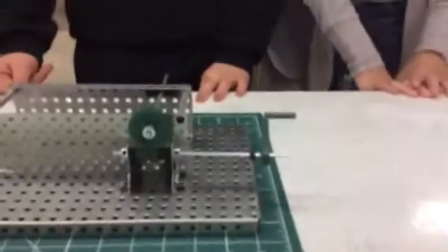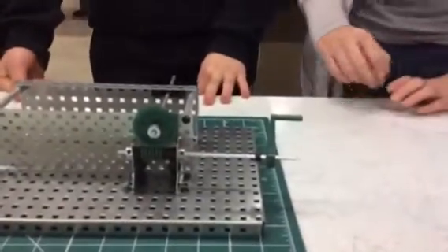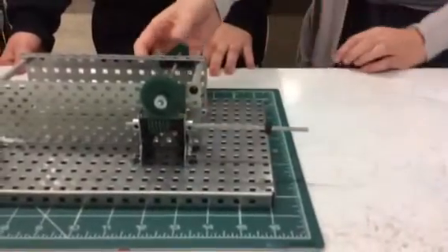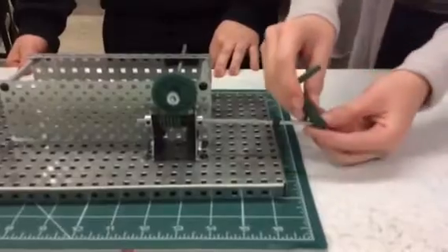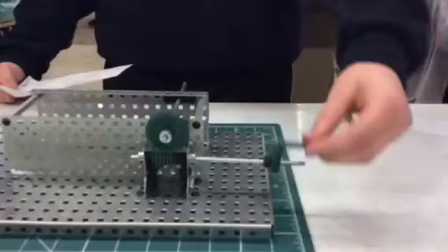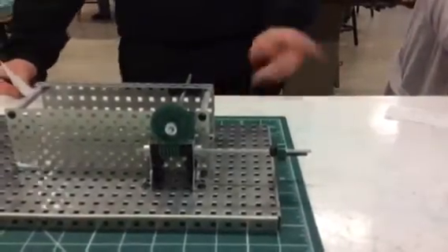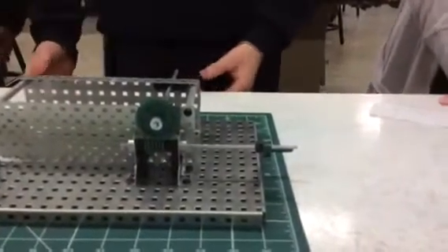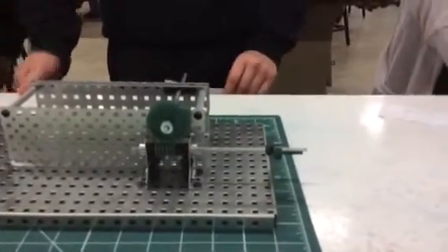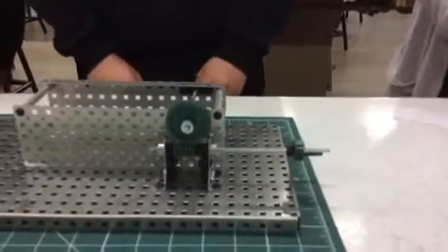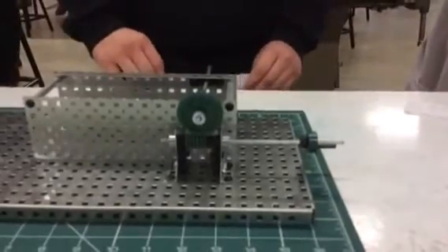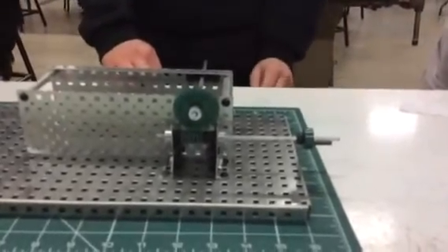The ratio is 24 to 1, and the flow of power is not reversible because you can't have this over here and expect both of them to move. So you have to have it over here. The direction of travel is reversible because you can move it left and right and it'll spin both ways. And then an example of our mechanism is on string instruments, on the tuning pegs. Thank you. Excellent. What type of motion is the input and output on your mechanism? The input is rotary and the output is rotary. Cool. Thank you very much.